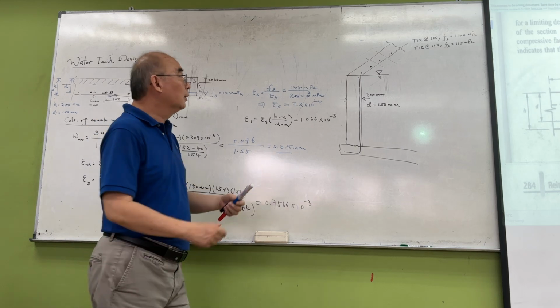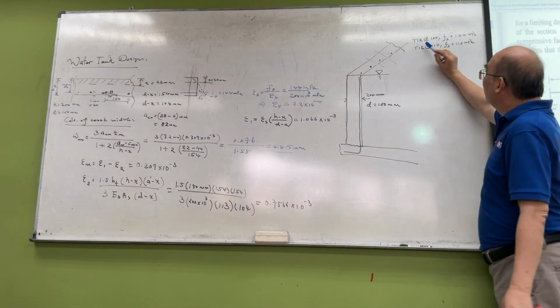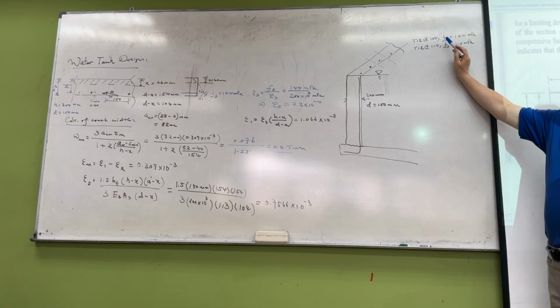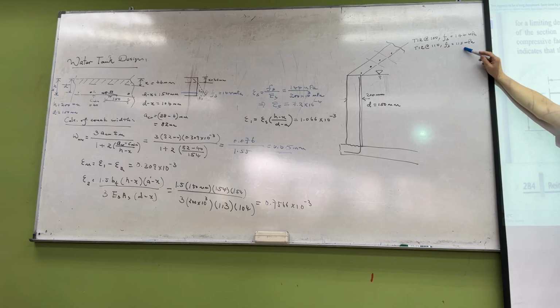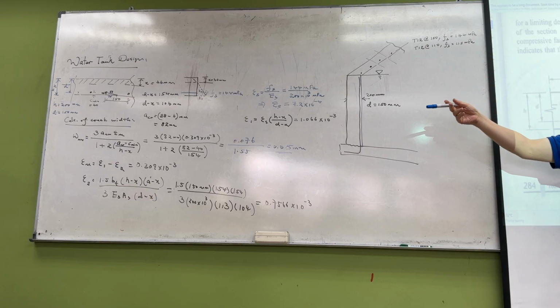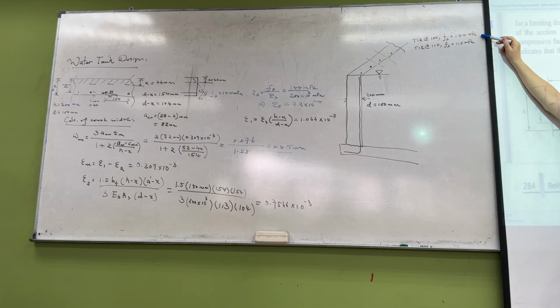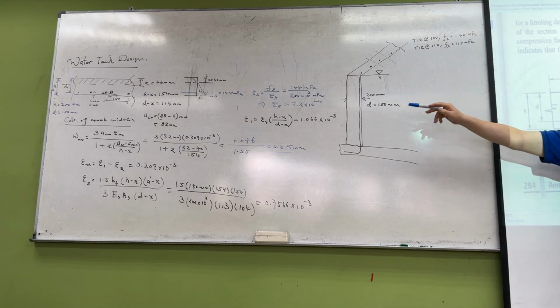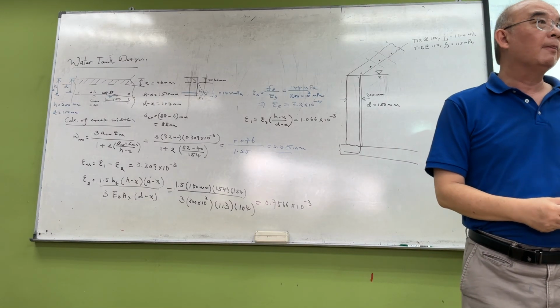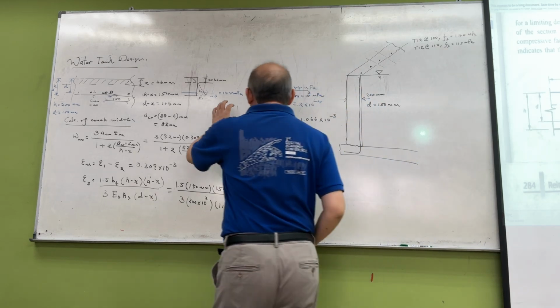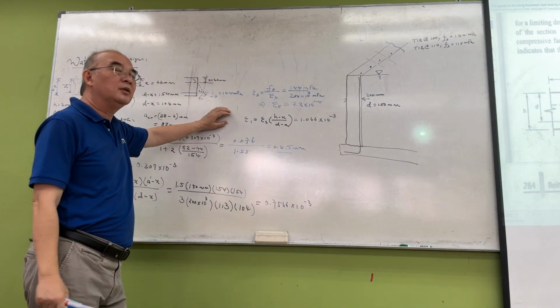Okay, so remember when we use the T12 at 150, our rebar stress is 144, which we say is not okay because it is more than 115. But as I said, this approach is actually more conservative. That's why I'm showing you this. That means even though the rebar stress is more than 115, when you calculate the crack width, it is actually less than 0.2 millimeters. So this is a more economical approach. That means it saves you money.